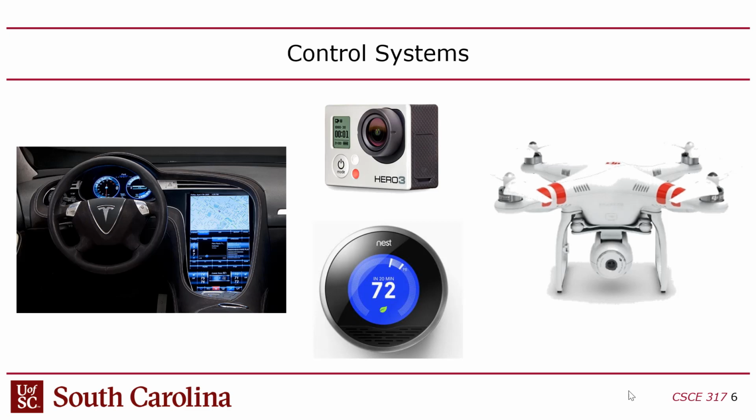So you choose what you want to focus on, and the camera uses a closed-loop controller to actually focus on that thing. Of course, in the case of a camera, the manipulated variable is turning the focus, and the process variable is read through the sensor. Different cameras have different technologies. They either use contrast detect autofocus or phase detect autofocus, but they have different ways to read the focus.